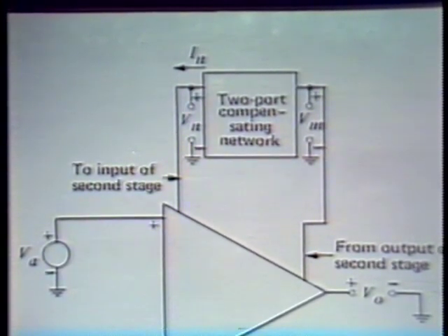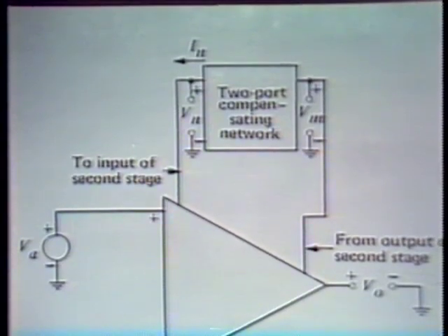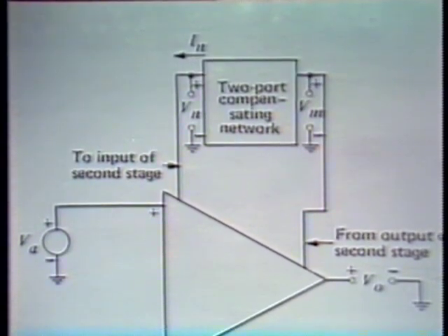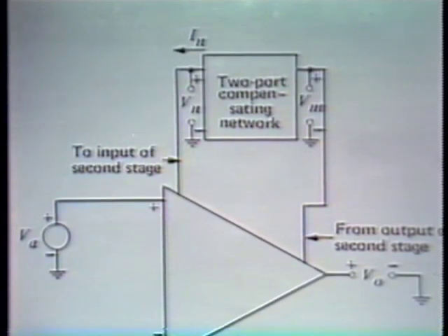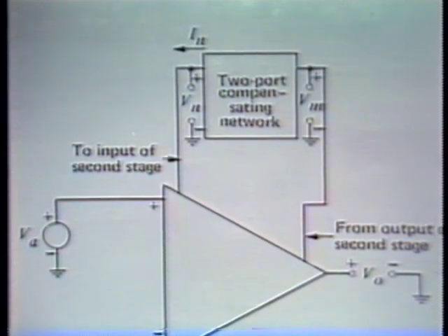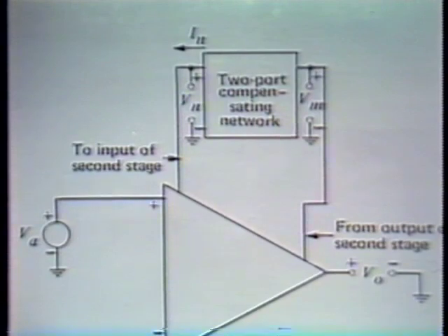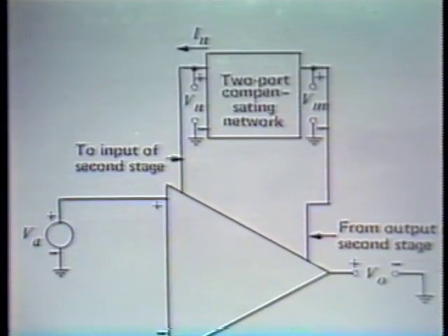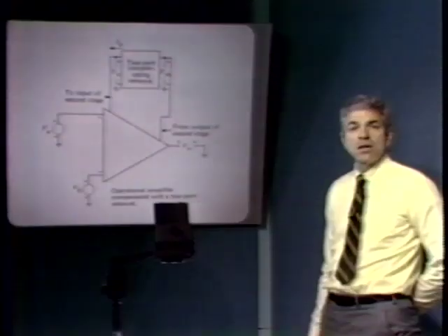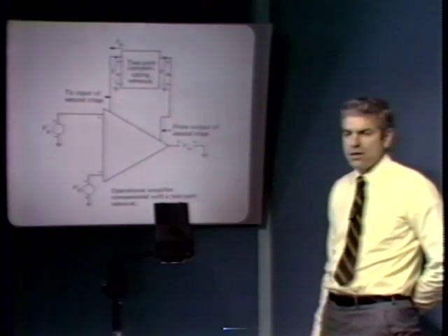And by using appropriate design techniques in these two-stage amplifiers, or amplifiers that have really only two stages of voltage gain, it's possible to get the kinds of open loop gains at low frequencies that one normally associates with operational amplifiers, somewhere on the order of 100,000 to 1 million. That implies a voltage gain, if it's equally distributed between the two stages, of something like 1,000 per stage.